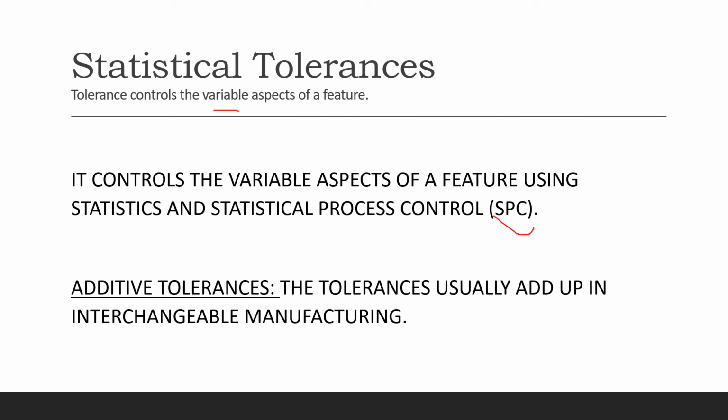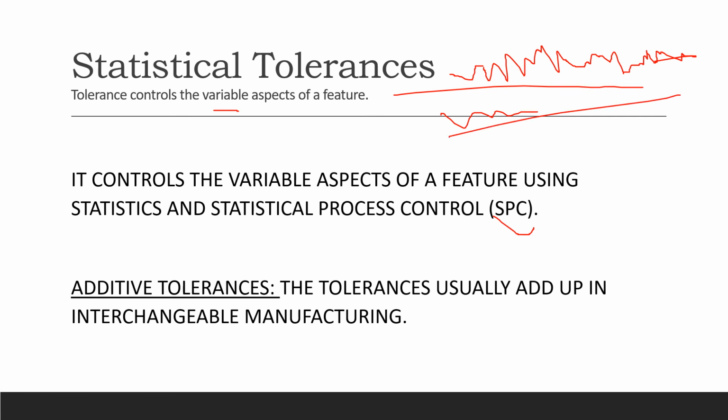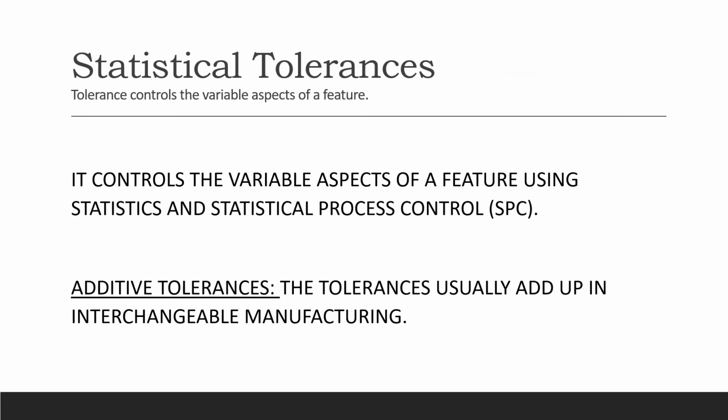We call that SPC. You sit at your table and check your production and processes, and they have to be within the specification limit that you determine. If they go up and down, it means there's an issue, and you're going to find the issue and solve it. So quality folks, my line is to solve issues, and most of the time you monitor, inspect, and do policing.